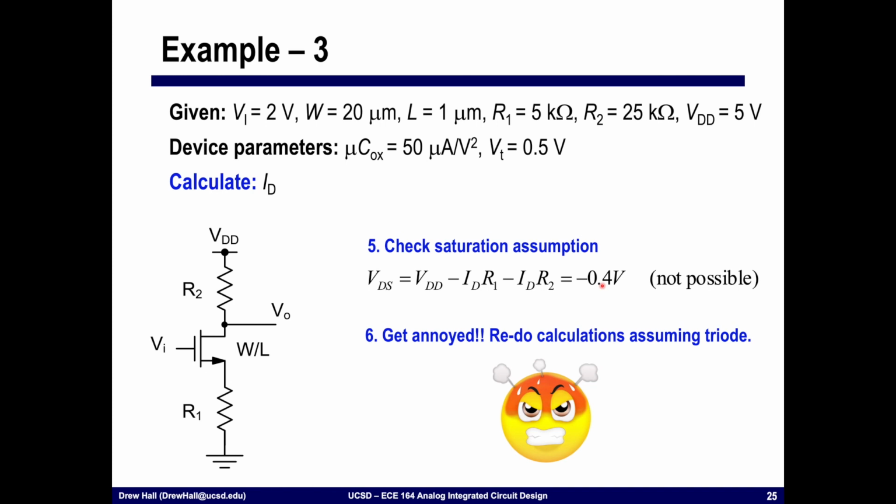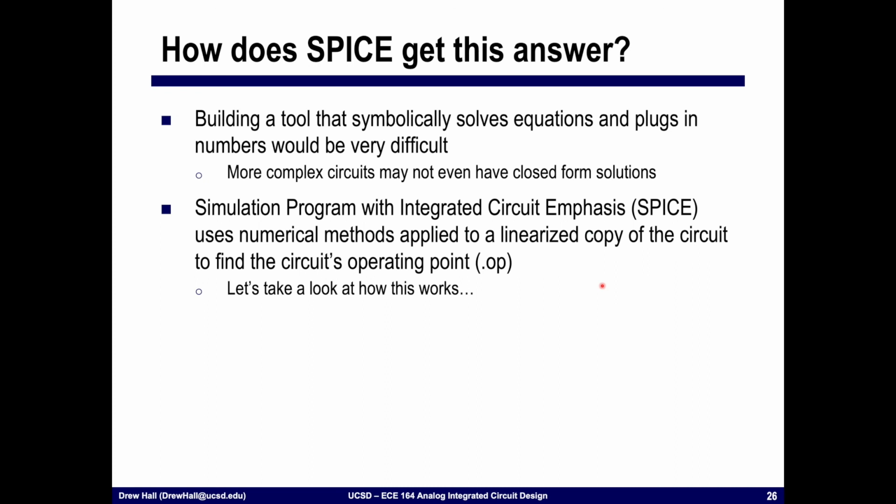So how would SPICE do this? SPICE essentially is going to do the same thing that we did, except it handles much, much larger circuits. This one transistor circuit is very easy. SPICE is not a tool that symbolically just solves these expressions and plugs them in. It really is nothing more than a matrix solver. It's a numerical method applied to a linear version of this circuit in order to find the operating point.